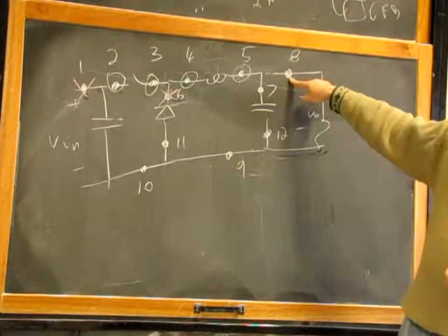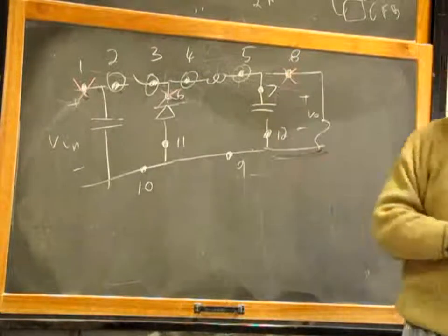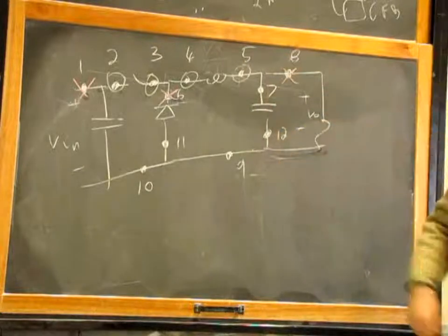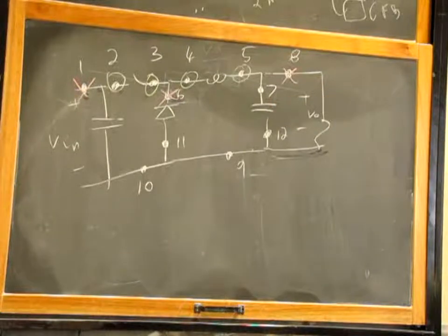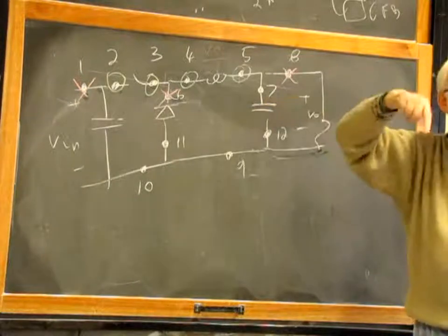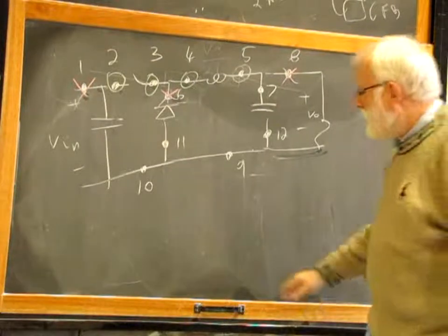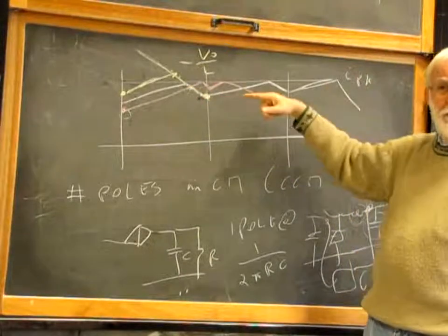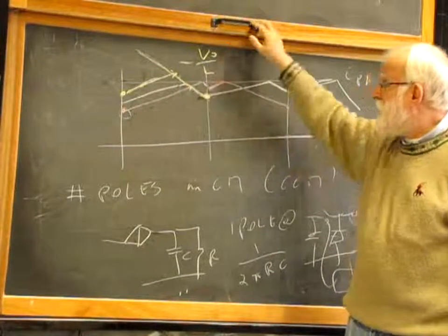What about 8? That's a no. Why? You see, it's just the average value. What about the current flowing to the output capacitor? Oh, I forgot the input capacitor. No, because there is also a secret. The current flowing through the capacitor is AC only. There is not the DC value. So when I use current mode control, what I need is the total current, not just the current ripple through the inductor. I need the actual current. How many amps are really going to the inductor?